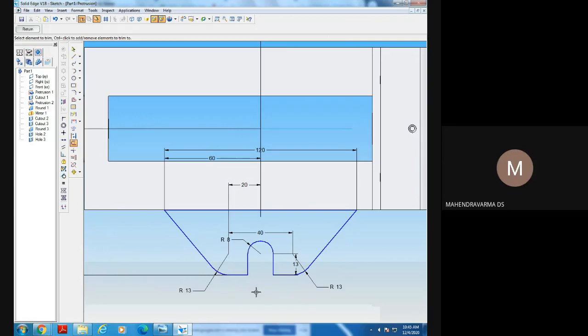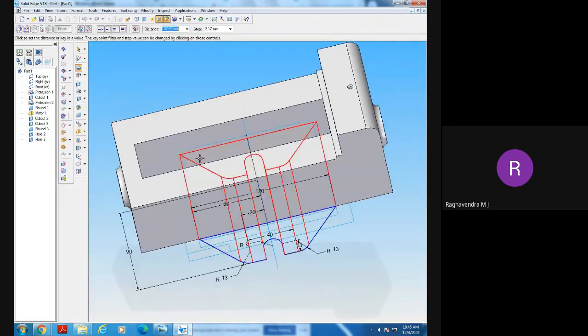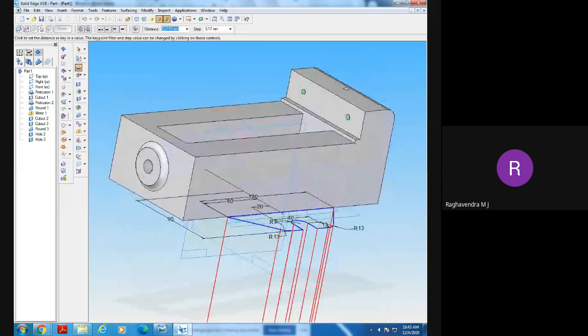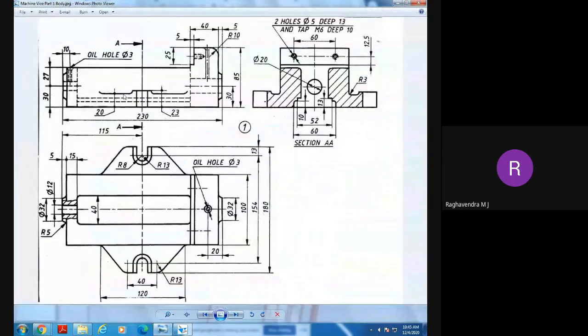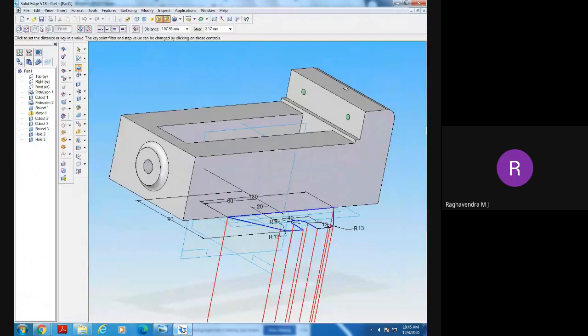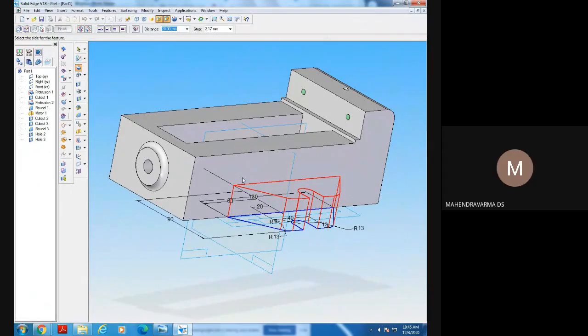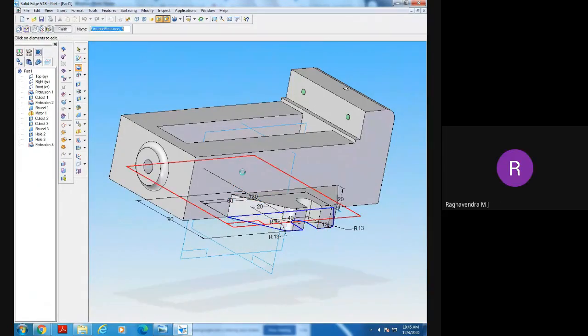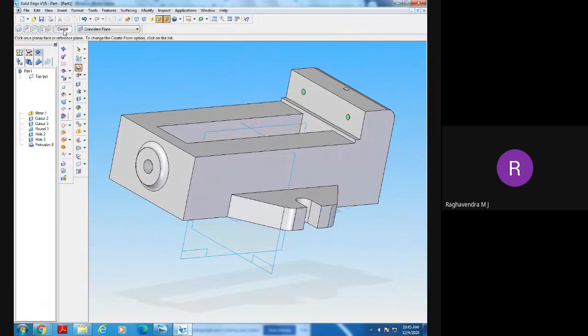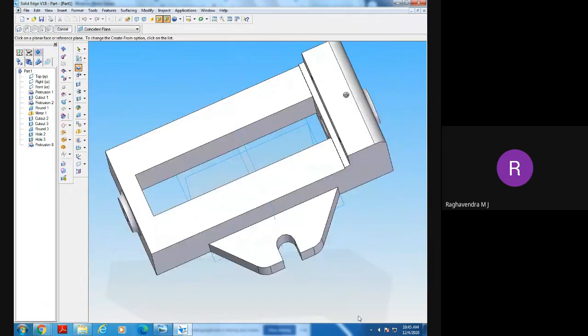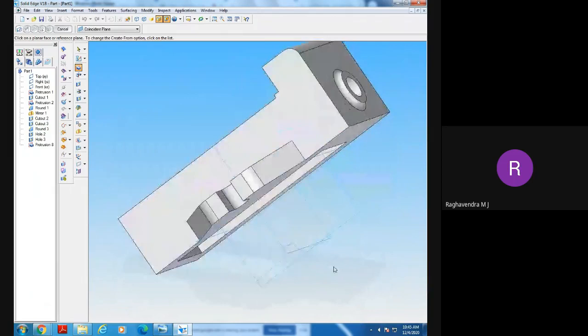No, sir. Okay. So now after this, at a time I am doing that, that's all, nothing else. Go to return option. Okay. How much protrusion I need? In the front view, it is 20. How much? 20. Okay. Enter 20 and place it. Finish it. It will come. See here. At a time it will come. See here. Are you able to see this now?